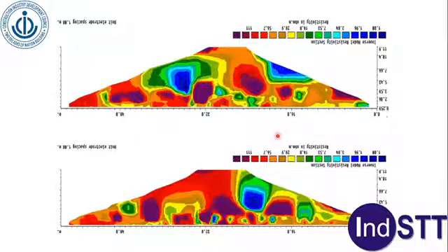So it's like CAT scanning. It provides piecewise information of the subsurface condition, and it's high resolution tomography. What we record is travel time and amplitude. There is one source hole, so this is a source hole, this is a receiver hole. We send a lot of these waves from source to receiver, and ultimately after inversion you get detailed information of what's happening between the two holes. Very detailed information. I'll show you examples like this.